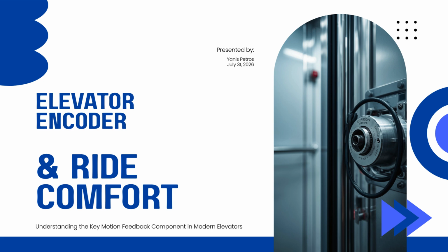What is an elevator encoder and why does it affect ride comfort? When an elevator starts with a jerk, vibrates at low speed, stops unevenly, or relevels repeatedly near the floor, many people immediately suspect the traction machine or inverter. But in modern elevator systems, the real issue may come from a smaller and less visible component: the elevator encoder.